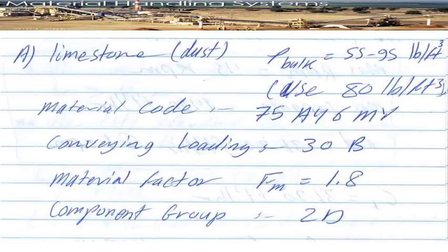All this data can be obtained from the table, but in the exam tomorrow, I will give you exactly the properties of the material you are going to use. The material code will be missing. If the material code is missing, just use the A46 value as A35. So your code, for example, if I use the same material, is going to be 75A35. And this will guide you how we are going to find the diameter required for the screw conveyor.